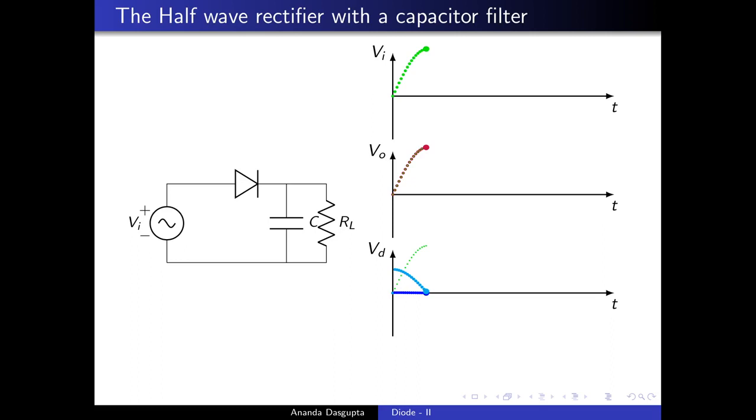At this point, the capacitor does not charge any longer. The diode current has fallen to nearly zero. There is a small current at this stage because there is a current flowing through the resistance, because the diode is still nominally forward biased. But now what happens is this, and this is where the actual action of the filter starts. Once the input voltage starts to drop from the peak, now notice what is happening.